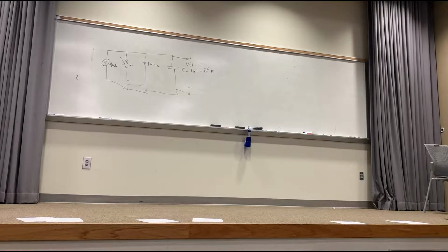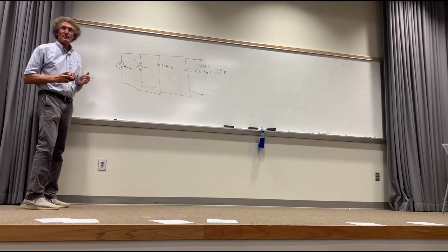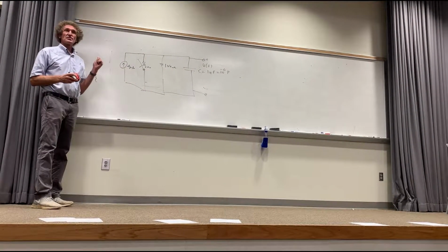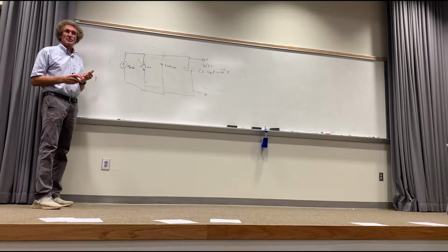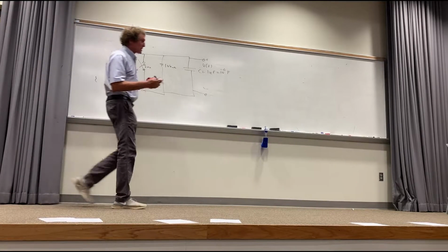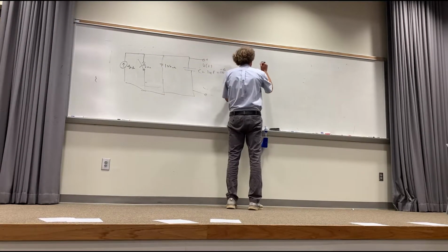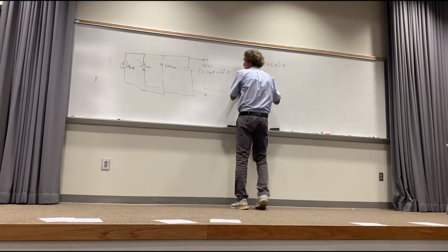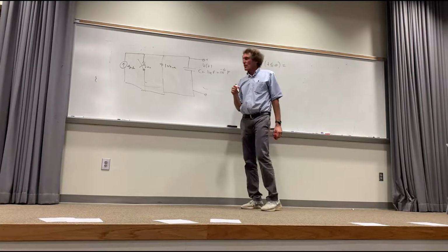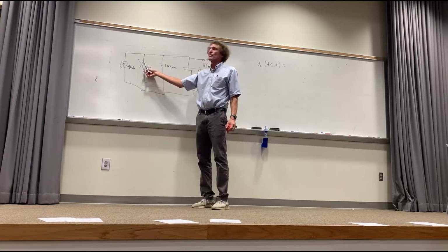All right, now to do this, the steps are straightforward. First thing you do is find the voltage before the switch closes. Correct, class? Before the switch transitions. So the VC in this case, voltage on the capacitor for t less than or equal to 0. What would that be? Well, the switch has been open forever, right?